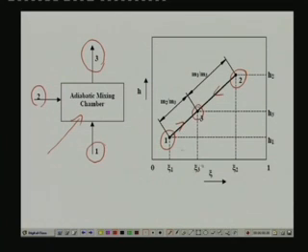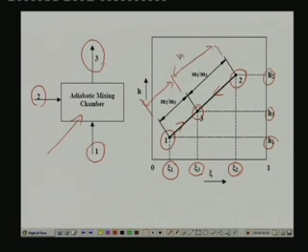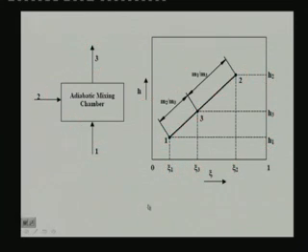So, you can point the composition: this is the composition of stream 1, composition of stream 2, and this is the composition of stream 3. Similarly, enthalpy, this is the enthalpy of stream 1, enthalpy of stream 2 and enthalpy of stream 3. And you will find that it can be easily shown, I will show you in a minute, that this distance is nothing but m2 by m3 and this distance is nothing but m1 by m3. How do you do that?